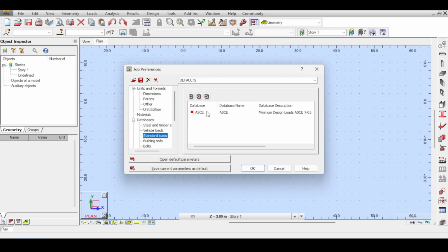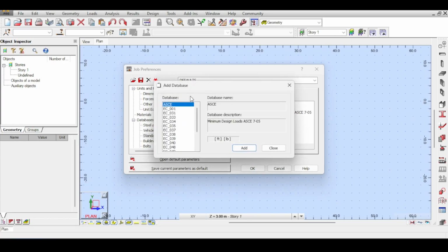Now standard loads is the ASCE. I will not have the ASCE. I want to use the Eurocode. So, okay, which one of those? Eurocode 1. How do you select that, right? All of them are EC1, by the way. All of them should be EC1. And it's strange that I have so many EC1s. It's kind of annoying. I see this EC1 because it's Eurocode Part 1, 2002.